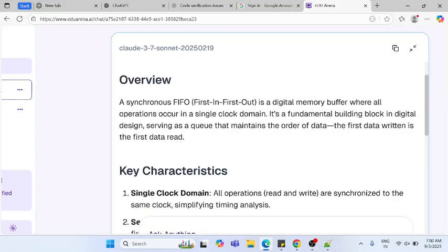If you think about memory, we have static RAM, dynamic RAM, and so on. But FIFO is something different from that, right? We discussed a static memory design also. In the static memory, we have a clock, reset, and a write enable or read enable. Write enable is a single bit, and based on its logic status, whether it is high or low, we can decide whether it represents a write operation or a read operation. Then we have address, data in, and data out.